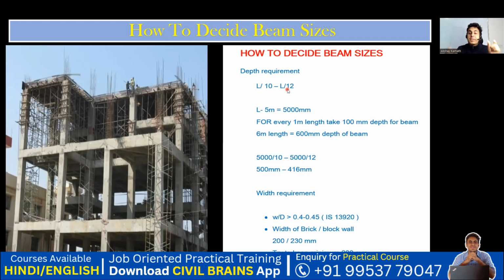What is L? L is the clear span. So what exactly is a clear span? For example, if this is a column that I have, and this is another column that I have, the distance from this center to this center, from here to here, is called my clear span. Whatever your clear span is, that is taken as L. So we are supposed to take the distance between the two columns and divide it by 10, or up to 12 we can say.